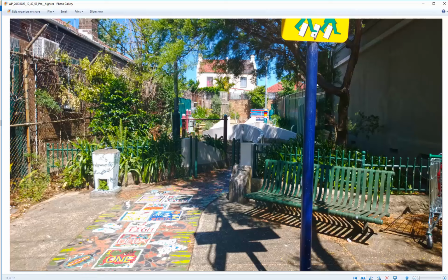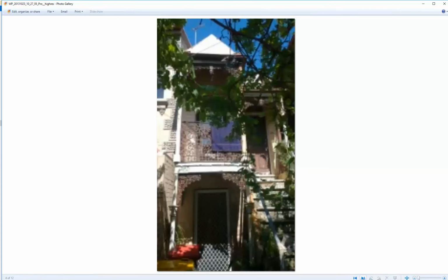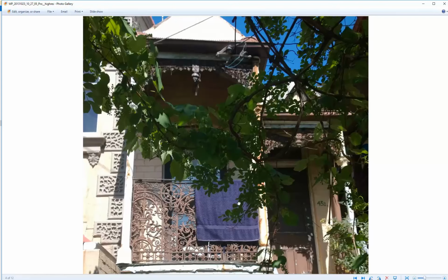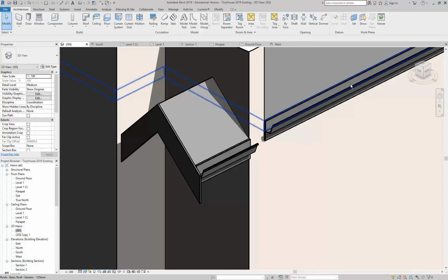But again, when you let builders make it up as they go, they do these things that are architecturally incorrect, but it works. But yeah, so you've got this gutter, and that one needs a downpipe. So that's definitely what I would have done. And I would even look at doing concealed downpipes here, because you've got these posts that essentially could work as downpipes possibly, or you could even look at concealing it somehow in the wall. There are a few different options. But exposed downpipes are okay as well. Downpipes can actually be a good architectural feature.